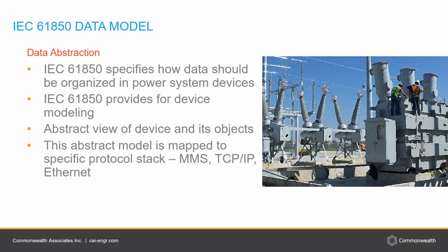So implementation of 61850 is not dependent on any particular type or brand of device being used. You can have relays or IEDs of a particular brand, and then you can also have remote input-output devices of a different manufacturer, all in the same framework of 61850. This is one of 61850's greatest advantages.